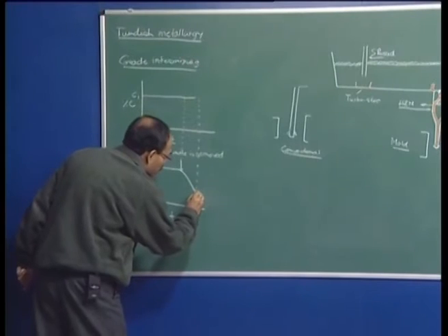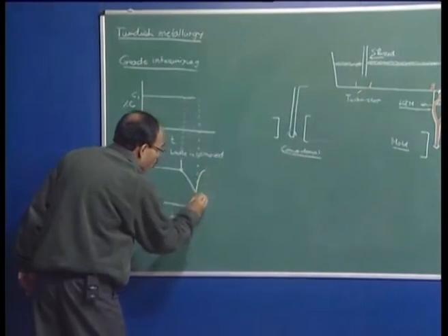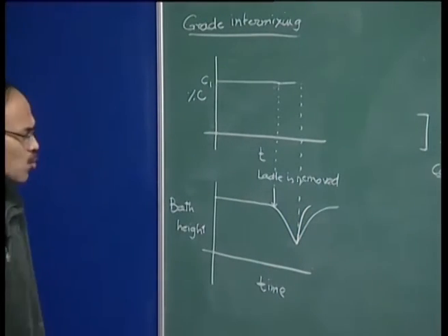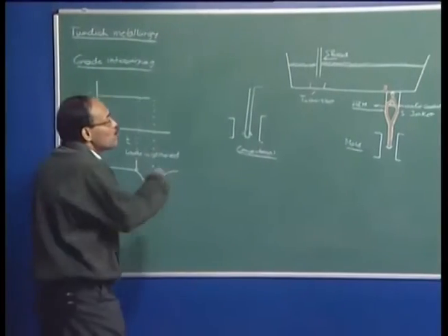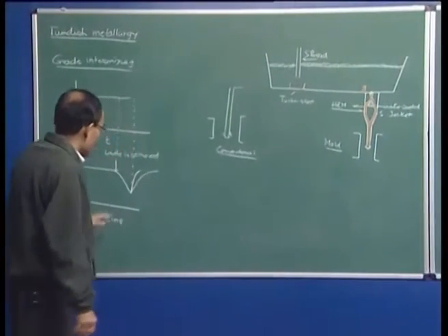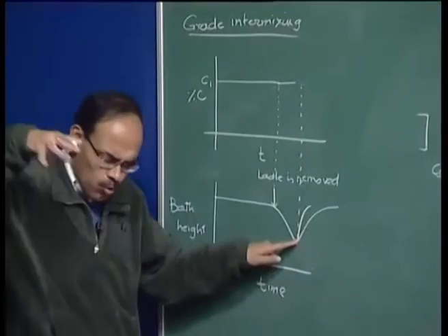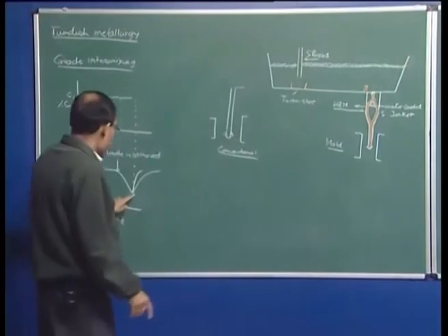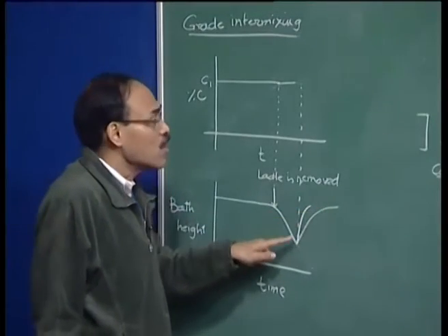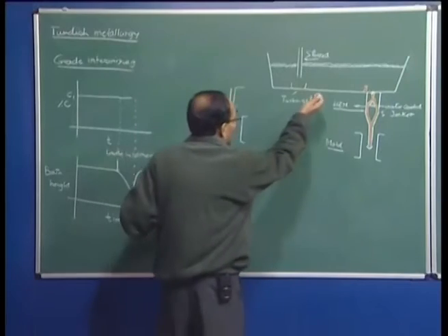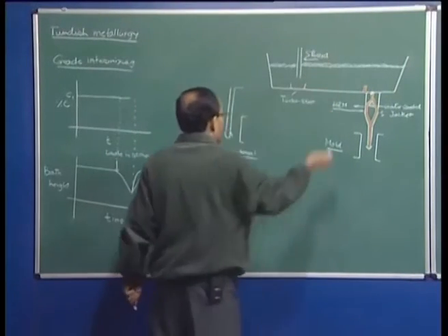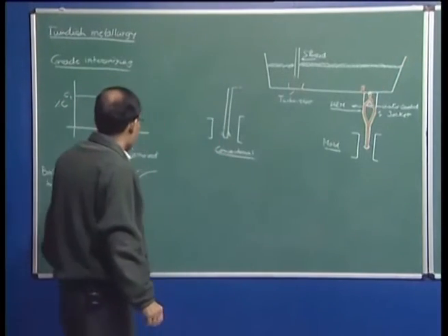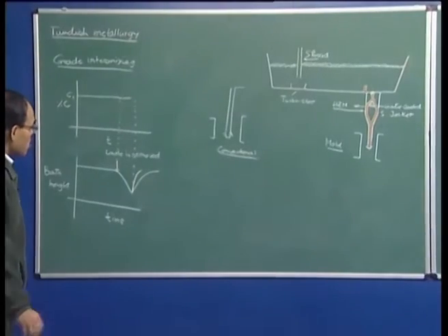Once I start to bring in the new ladle, the bath is going to rise immediately. The bath can be made to rise very steeply or slowly depending on the process performance. We do not want to lose time. Also, we do not want too much slag emulsification. If you try to pour in molten metal at too fast a rate, refractory damage is going to be there. On the other hand, if you pour too slowly, the rise in the bath level is not going to be significant, and as a result the casting rate may be hampered. So, somewhere in between.